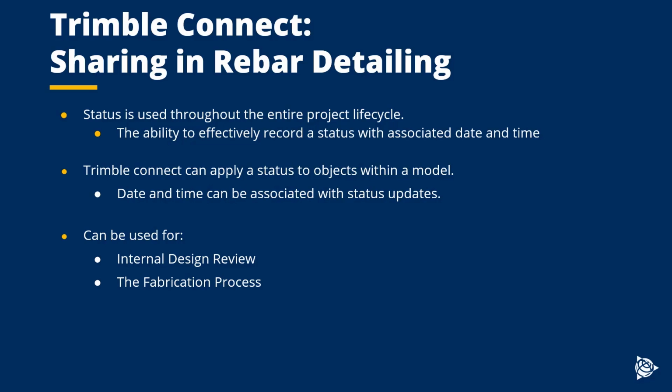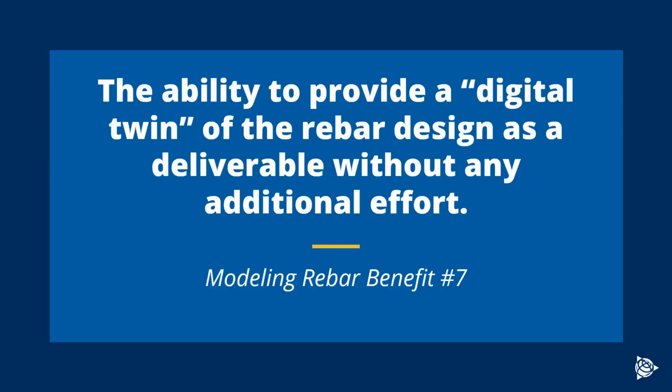Status sharing can also be accomplished from the field via your mobile device. As the bar is being installed and the embeds are put in and the formwork goes up and then the concrete comes in, you can status all those different stages throughout. So by detailing our bar in a BIM platform such as Tekla Structures, we can provide value to our customers who have to actually execute that work. The concept of status sharing is pretty straightforward.